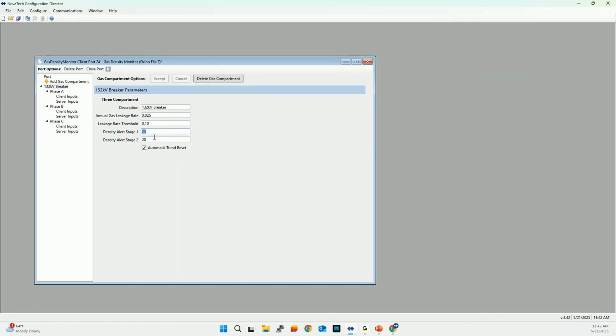And this is also probably from the manual, they'll tell you when it should be noted that you should replace the SF6 gas or that it needs maintenance. And this is, it needs maintenance really, really now, stage 1. Basically the equipment is almost close to lockout.